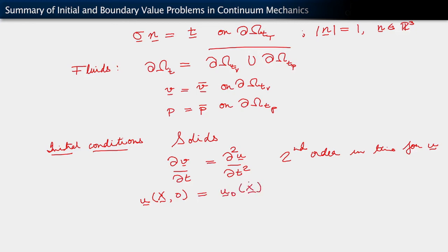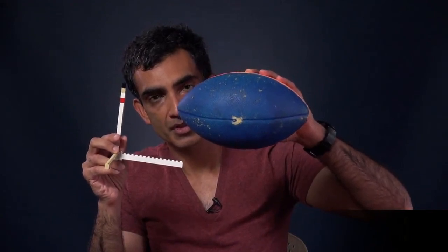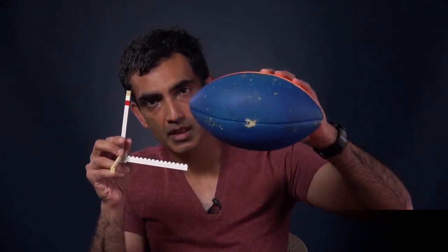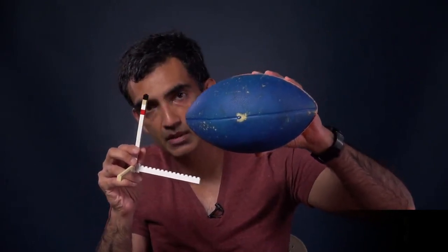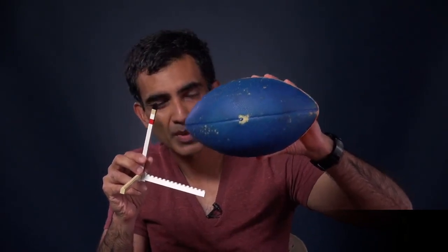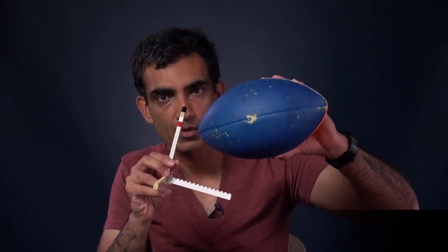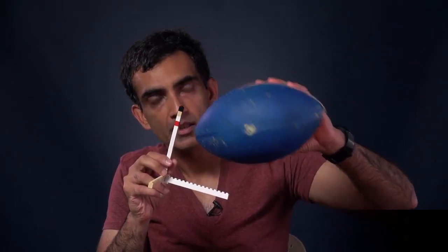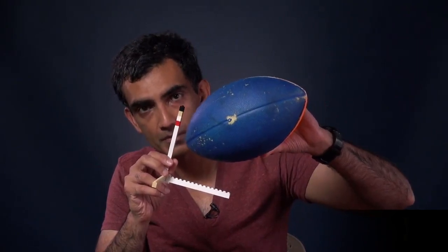Looking back at the displacement field parameterized with respect to reference position, we're saying that the points of the body have a certain displacement. It's typical in solid mechanics, because we think of this as the initial position, to require that at time t equals 0 the displacements are 0, because we measure the displacement from here. So that is a typical condition.